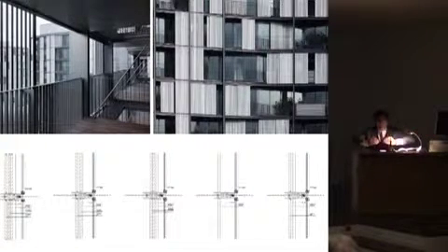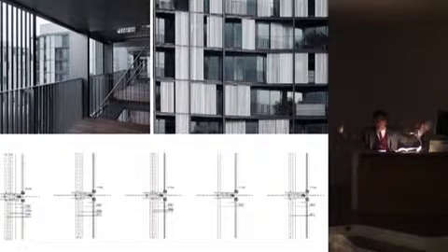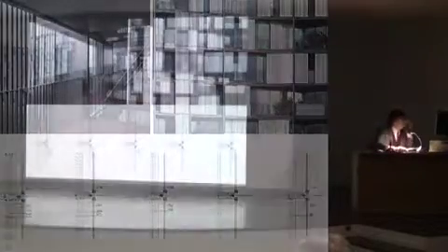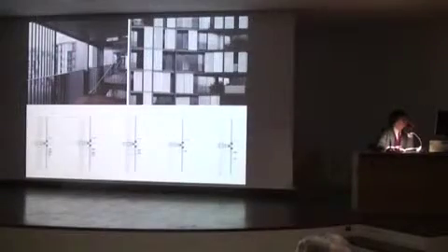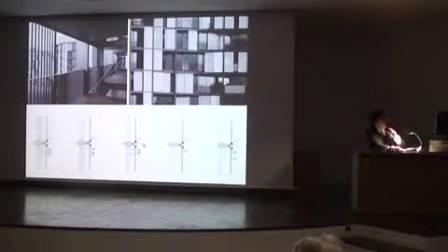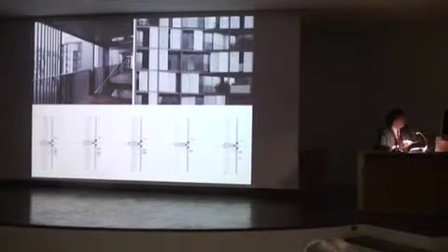So you need to place a drain pipe just in the end of the floor covering, where the handrail will be fixed and where the blinds will be fixed. So you create a mini gutter there, and the mini gutter, well, is then loading the weight on the jambs with the whole substructure of the facade, and you see the drains there collecting the water from the terrace. So the terrace is bigger, you know, with the cable there.